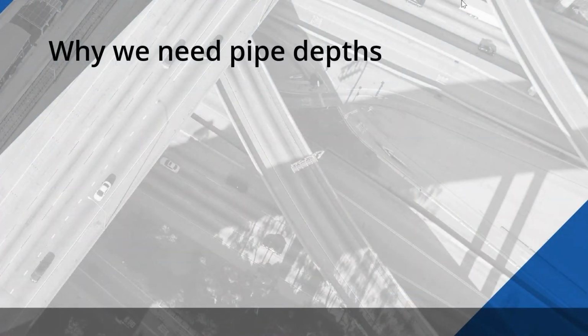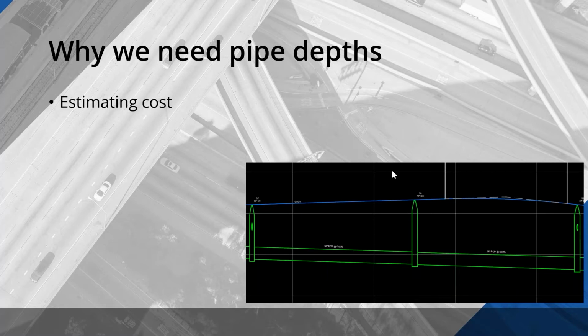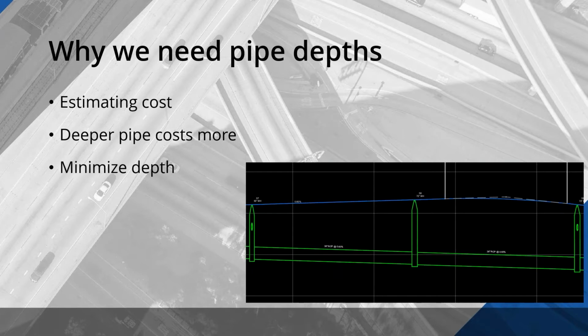Why do we need pipe depths? Let's answer that question first. What are we talking about? Why do we need them? We want to understand how deep pipe is to be buried or installed to help estimate costs. Deeper pipe, obviously, is more work to put in, so it costs more. We want to understand what that's going to be. We want to certainly minimize depth where it makes sense. We want to also ensure that minimum covers are met.